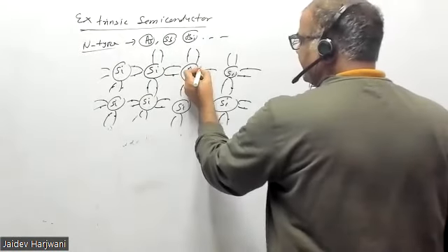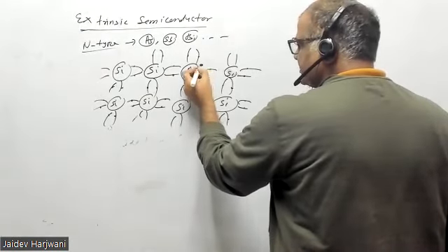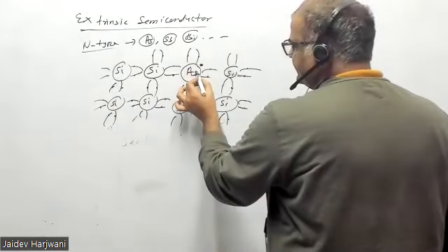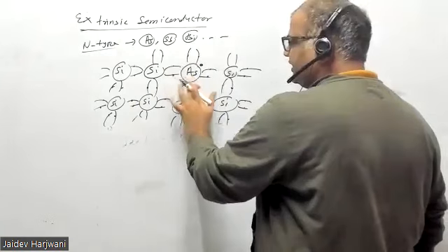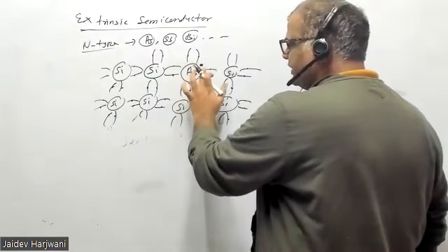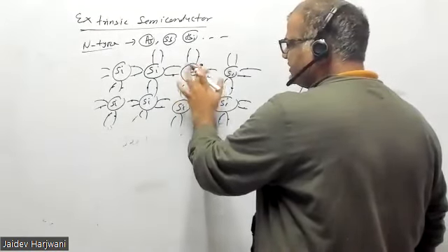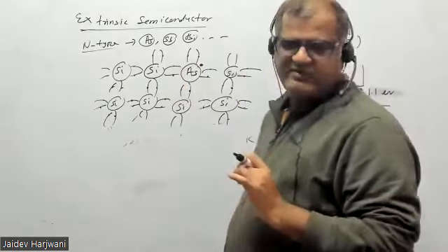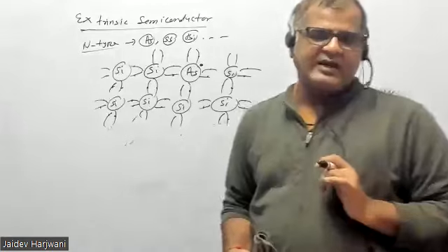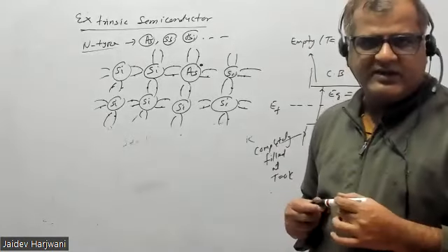This arsenic atom has an extra electron which is not bonded. So you can assume this is like a neutral core with a nucleus, and one electron is free, like a hydrogen atom. That's why we say impurity atoms behave like a hydrogen-like atom in the semiconductor.